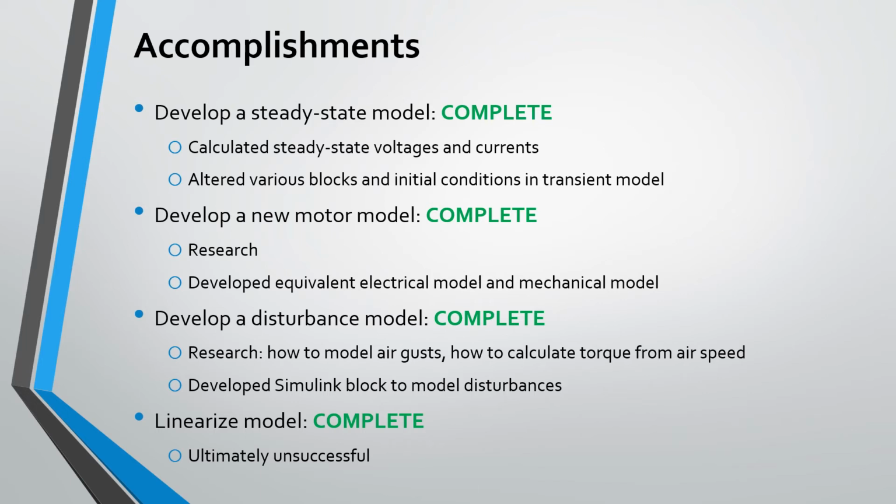Then I created a disturbance model. I read journal articles on how to model air gusts and how torque can be calculated from airspeed. I took this research and created a Simulink block that will model disturbances. Finally, I attempted to linearize the model using Simulink's linear analysis tool. Ultimately, it was unsuccessful because our model is too complicated to be analyzed using the tool.